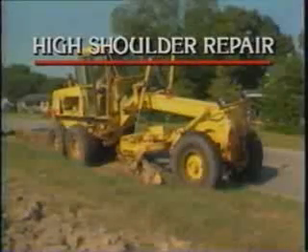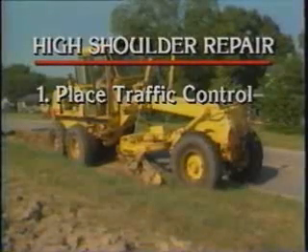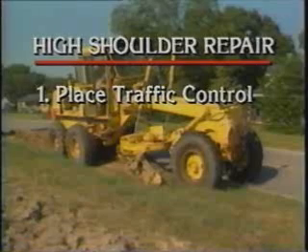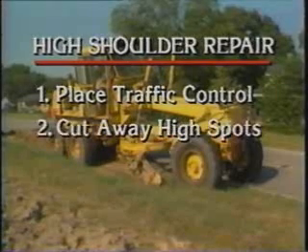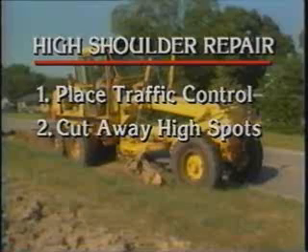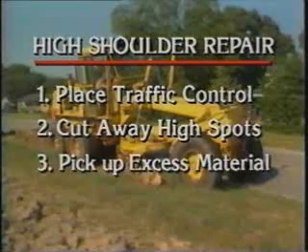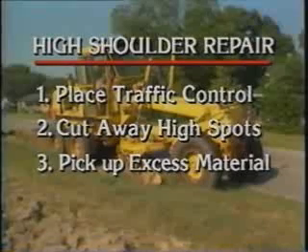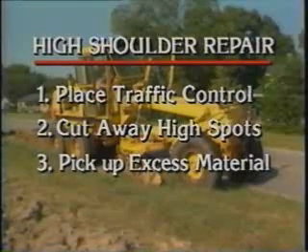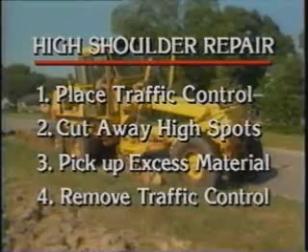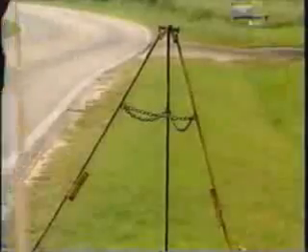The steps to be taken in this operation are: number 1, place proper traffic control. Number 2, cut away high spots on shoulders with motor grader. Number 3, pick up excess material and dispose of it properly. Number 4, remove traffic control.